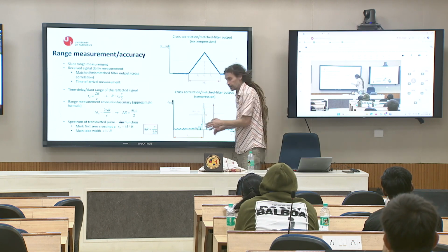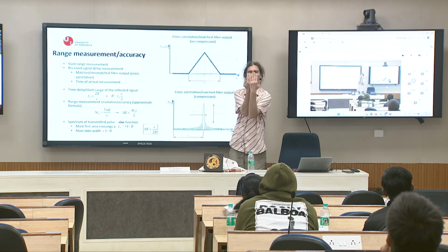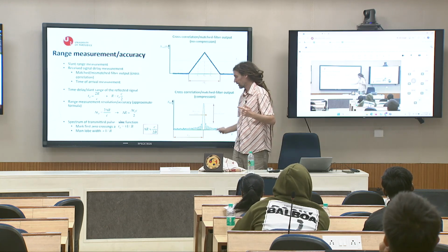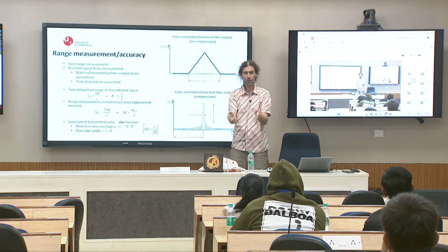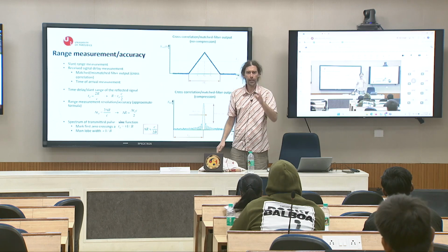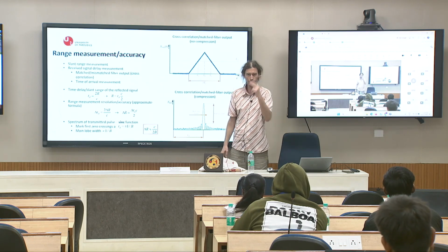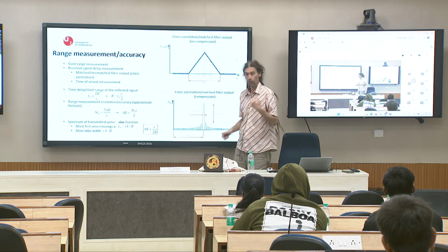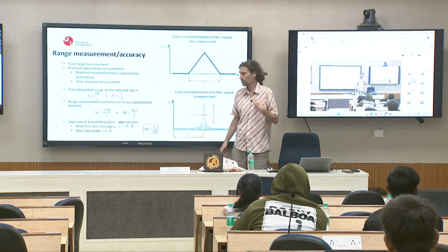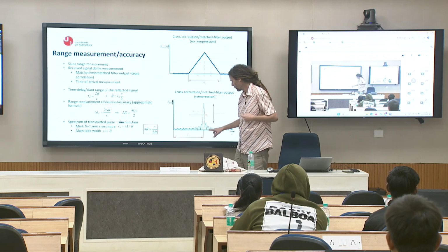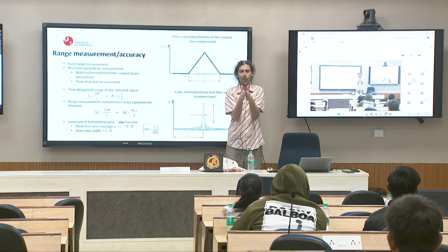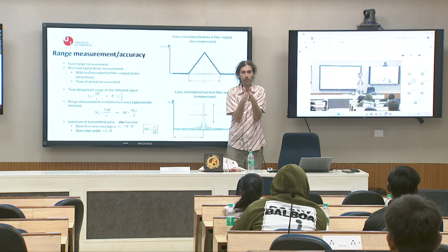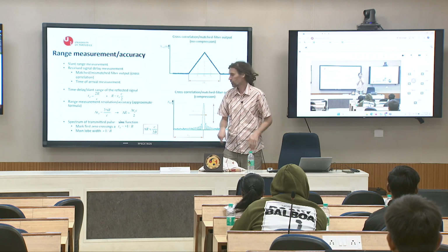They could be hidden, interconnected, just two sinc functions, and it will be one wide main lobe, and you think it is one target. No, it is two, but you don't have enough resolution. So it would be best if the side lobes are zero and all the energy is in one very narrow peak. It means better, higher resolution, I can recognize two targets, and it is based on this.